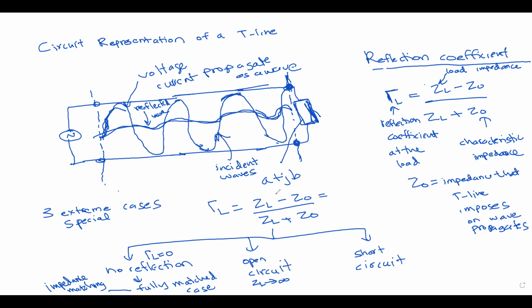So we need to divide each component of this equation by ZL. Once I divide each of these parameters by ZL, I get 1 minus Z naught over ZL in the numerator and 1 plus Z naught over ZL in the denominator. Once ZL goes to infinity, the final value of tau L is going to equal 1 plus 1... sorry, 1 over 1, which is 1.